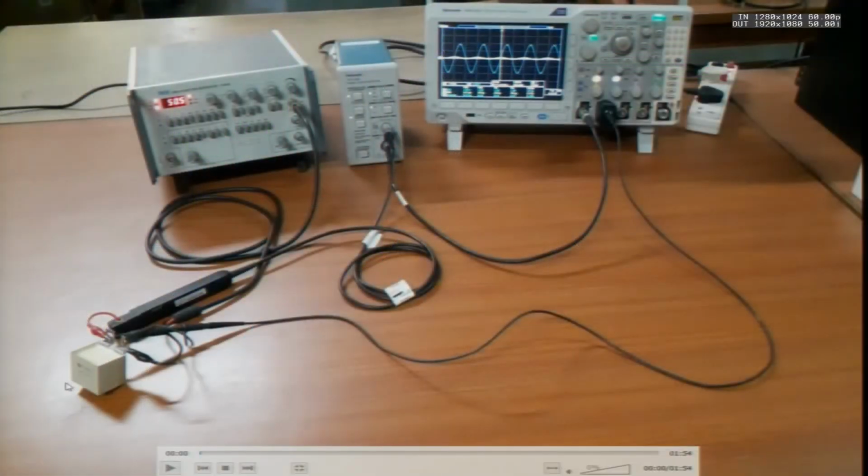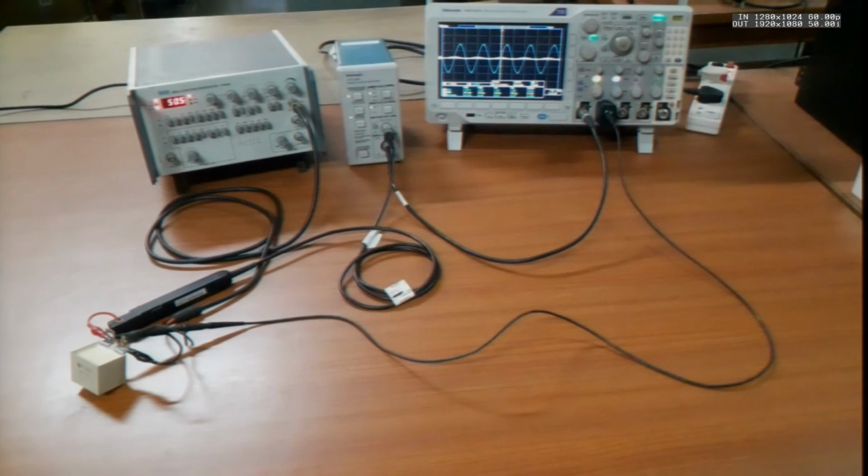Yeah. So, we used a capacitor which is shown here, and that was 1 microfarad. So, I will just quickly go show you there. Yeah, this was a 1 microfarad capacitor, and when we tried to do the experiment on this, we could actually see, at least in a very large frequency range, the capacitor indeed behaved like a capacitor. At least this capacitor behaves like a capacitor right up to 1 megahertz. It predominantly has a capacitive effect. We do not see any major non-ideality there.